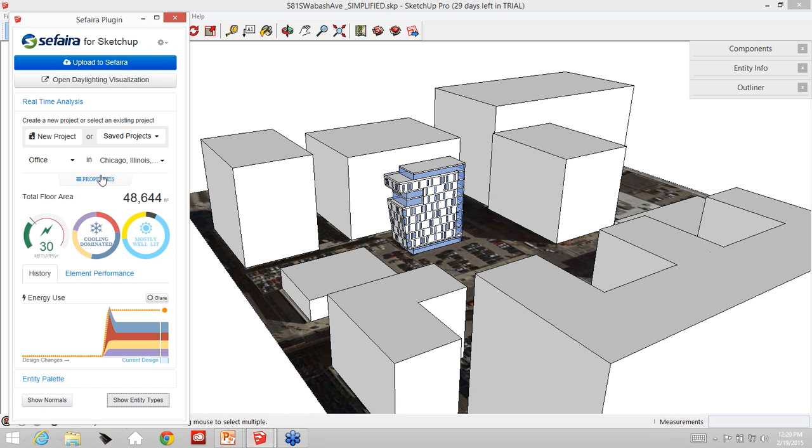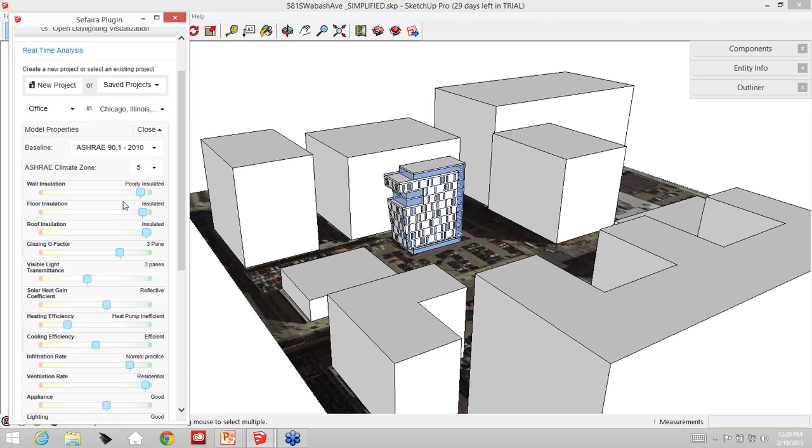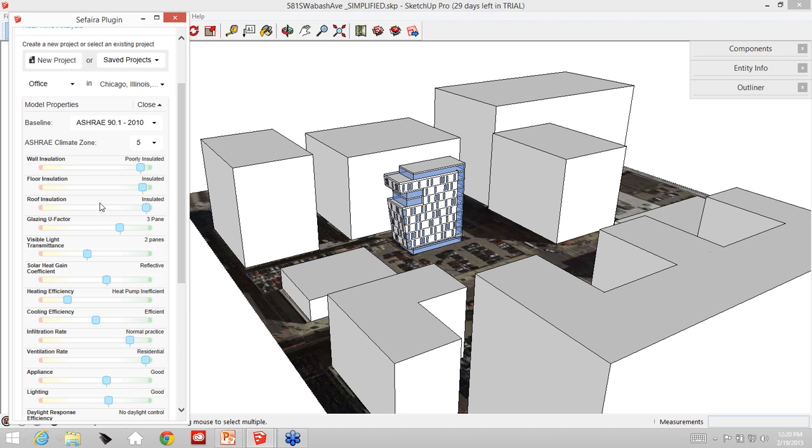And then the fourth input is the building properties themselves. So if you're involved with architectural design, you know that after the design concept is achieved, you have to do some detailed work around the building components, like the building envelope, the type of glass you use, the wall type you use, etc. And so this image here, this is where you change and modify those properties in Sefaira.